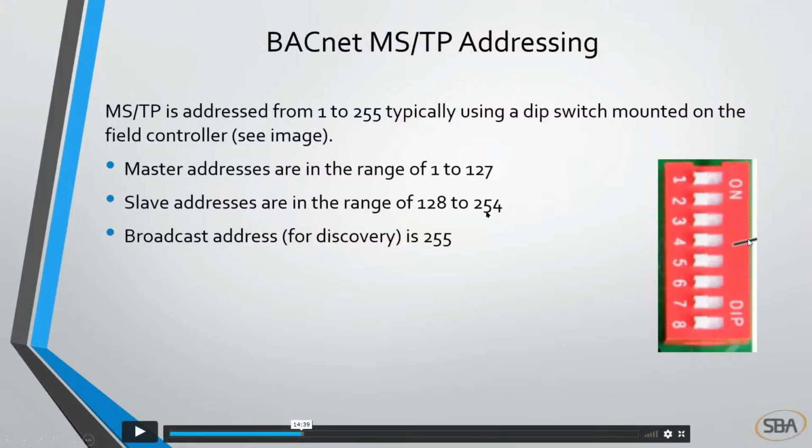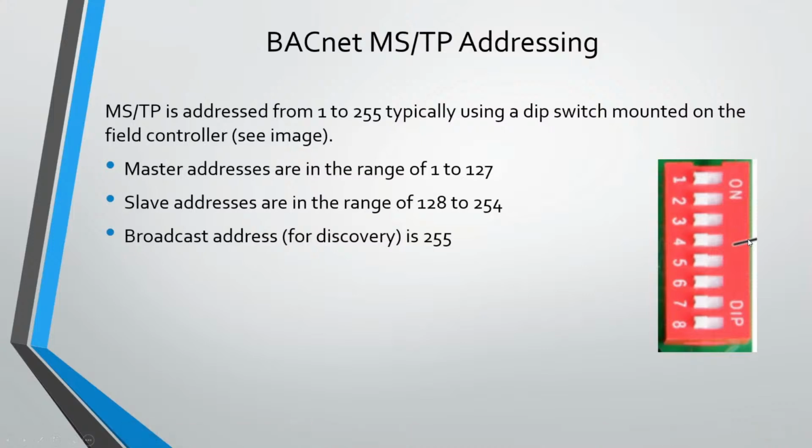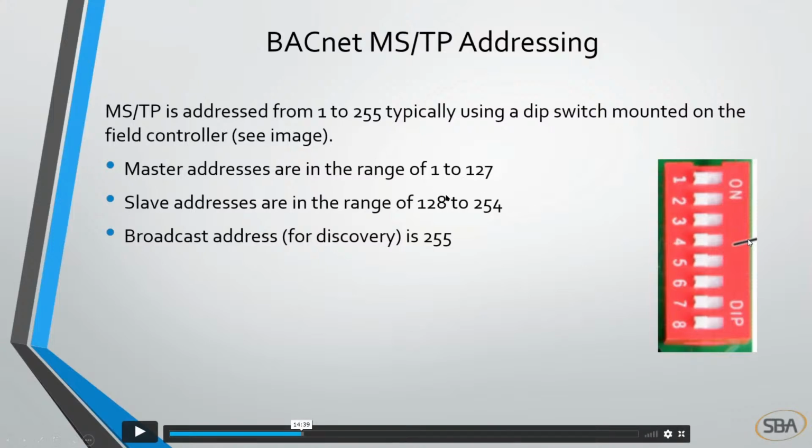So they allow dumb devices basically to be added on, usually for monitoring only. Remember when we looked at BTL and we looked at initiators versus executors of services? Well, this is where these things can be executors of a service typically, but they're not going to be initiators of a service. They're like dumb devices that only feed out data. Things like sensors, etc., right?